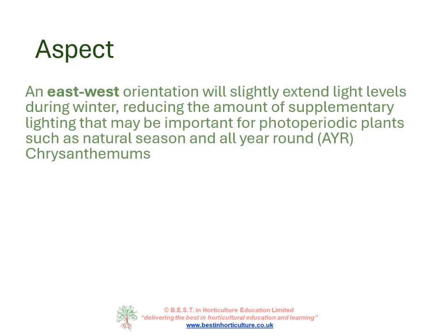The aspect required for a successful greenhouse or protected structure: an east-west orientation, that is with the ridge running east to west, will slightly extend light levels during winter. This reduces the amount of supplementary lighting that may be important for photoperiodic plants, such as natural season and all year round chrysanthemums.